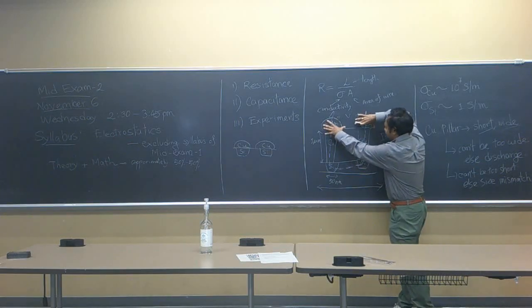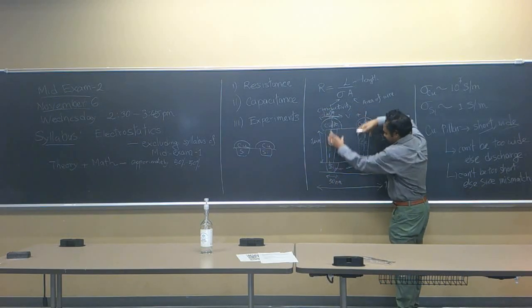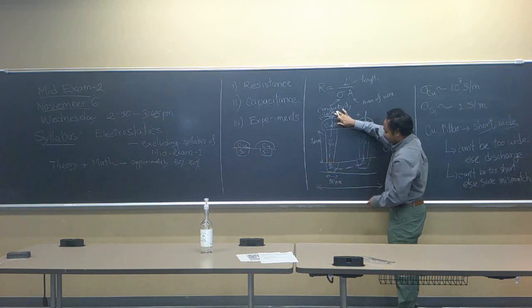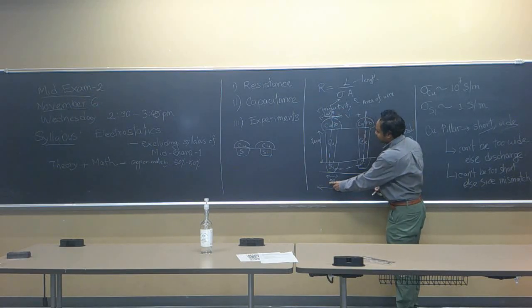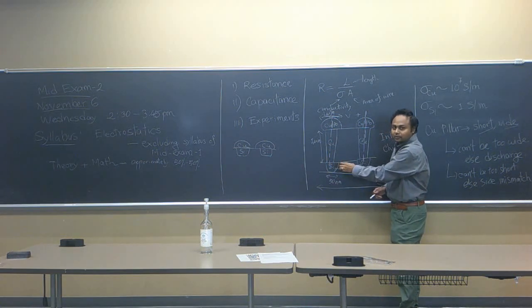If you make this copper pad very wide, say each pad has a size of 1 micron, can you put a 1 micron cap on a 50 nanometer silicon device? Remember, 1 micron is 1000 nanometers. This is very small, so you cannot put a big cap on the small die. Why can't you?